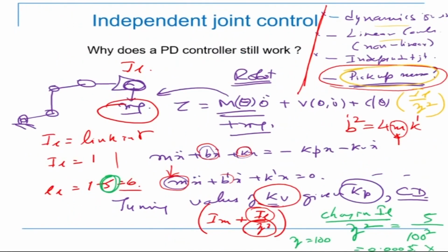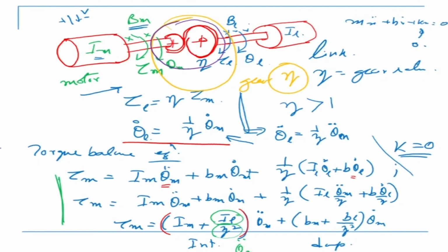Whenever I drew the system, I had a motor, a gear in front, and an encoder at the back. This gear has this zeta, and without it you'll not be able to control the system. The gear also ensures that whatever change in inertia is happening becomes very small and can be ignored, which means you have to have a high gear ratio.